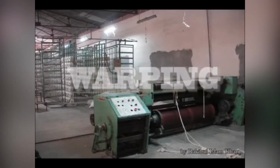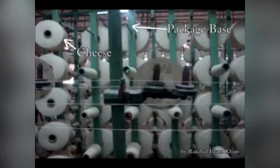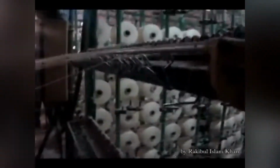Warping is the process by which the warp yarn from the cheese or cone packages are wound parallelly on a warp beam. First, the cheese packages or cone packages are set on the creel of the warping machines. Then the threads from each package are passed through various guides and laid parallel on the beam. Then as the driving drum rotates the beam, the warp yarns are parallelly wrapped onto the beam.